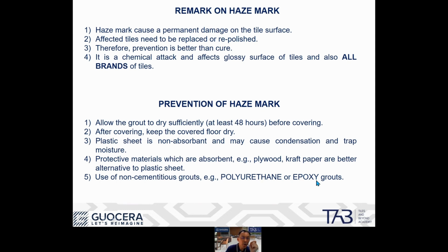They are slightly more absorbent than plastic sheet. And of course, the site will always come back and say these are more expensive materials. But the important thing is, we now know the haze mark is caused by water, and if water can be eliminated or prevented from going beneath the sheet, then you can prevent the haze mark.